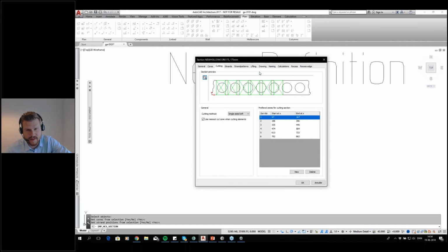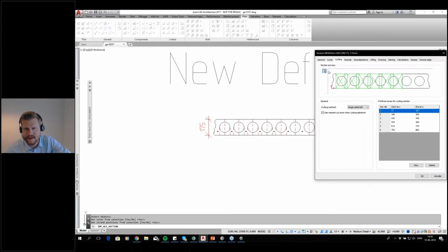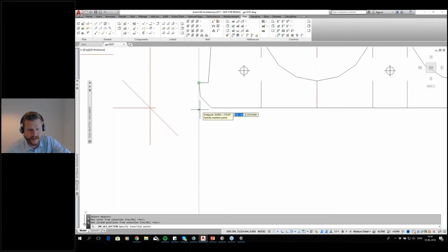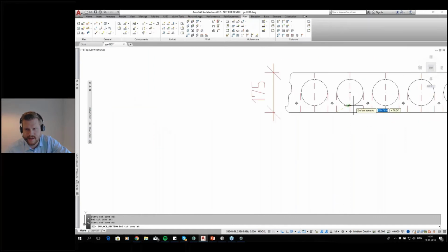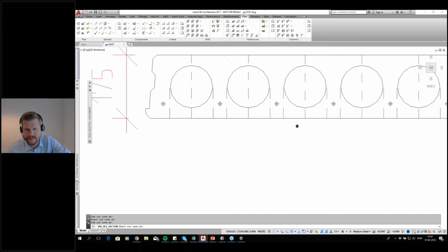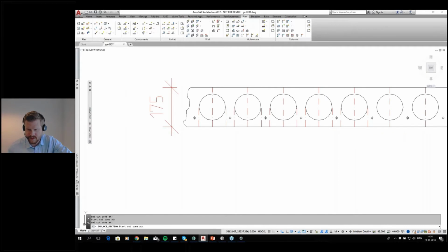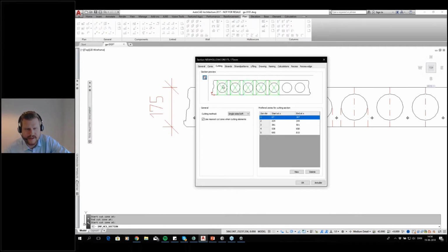Cutting here is the old cutting, and that's where these red lines that I did come into play. So I want to do the same thing here. I want to select cut zones instead. So now I need to select an insertion point and then select cut zones. Start, end, start, end, start, end. Just really, really simple. I just want it to snap to completely the correct place. There we go. Enter when we're finished, and now we can see it's allowed to cut here.